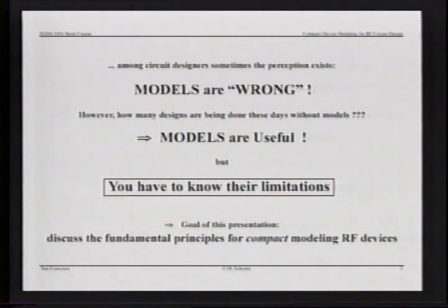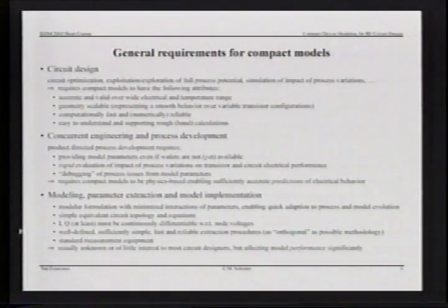So usually, if you design something, you have to know the limitations of the model. You can't design power amplifiers with a model that doesn't cover high current effects and saturation in the bipolar transistor. And that's a little bit the goal of this presentation, to discuss some fundamental principles for compact modeling of RF devices. So you should get an idea how models get constructed and what is important.